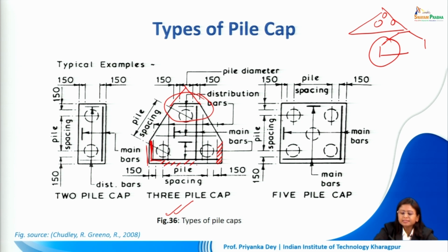We had studied this even when we were doing the grillage foundation in the last lecture, where we had learnt that a proper concrete cover has to be given to ensure that the reinforcement at any point doesn't become exposed, which may lead to corrosion. So proper cover has to be given, and we have to chamfer the edges because it becomes very difficult to create triangular corners in the foundation construction.